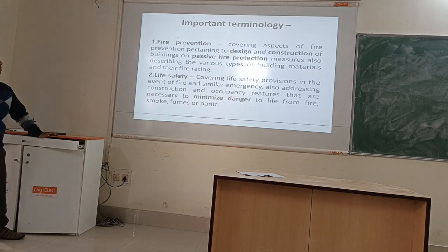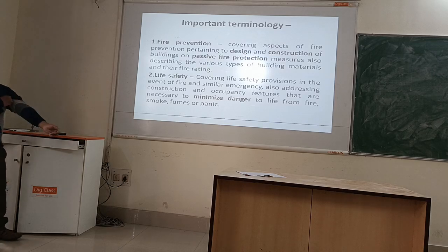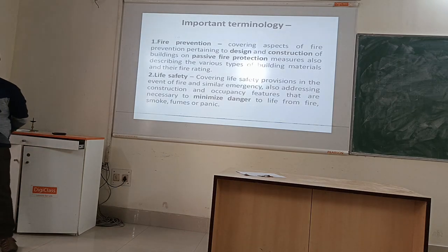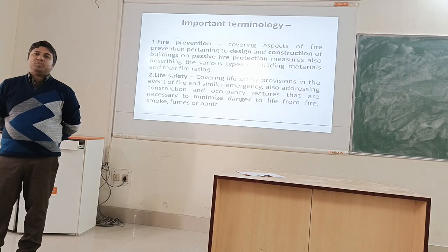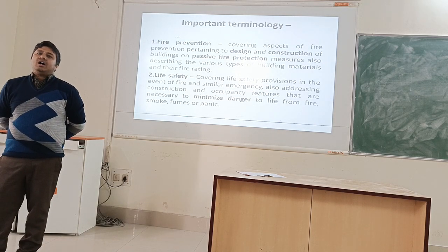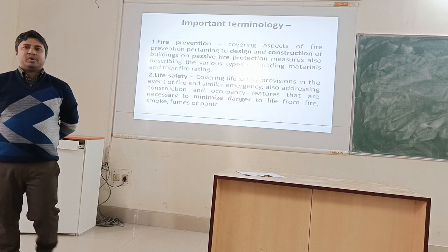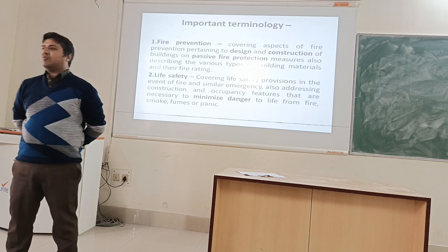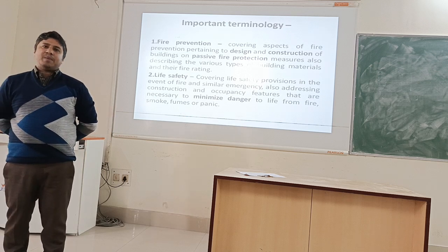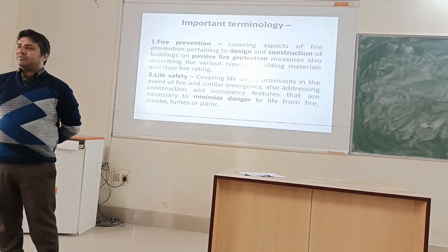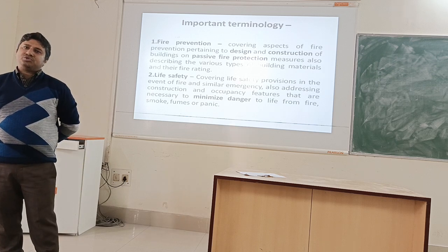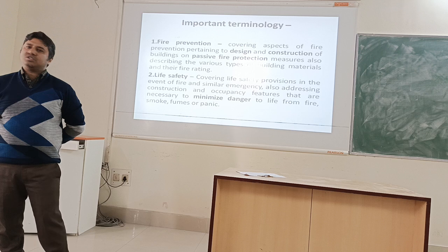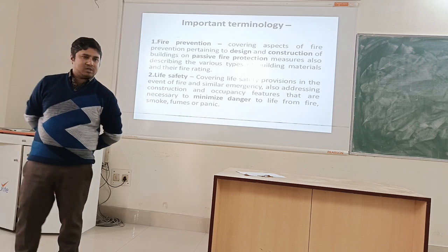Okay, fire prevention. We have to make sure that the design of the building is such that it will be able to mitigate the fire. The location of the firefighting should be such that it will be able to pass the extinguisher, in the form of water. Water, a high pressure pipeline that is carrying water, that is your fire hydrant. That should reach every location of a residential building. That should be the planning of how it is done.